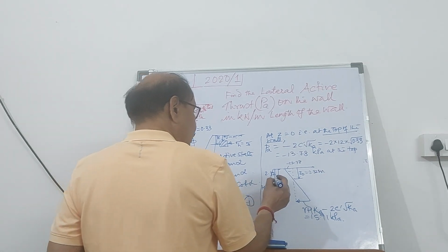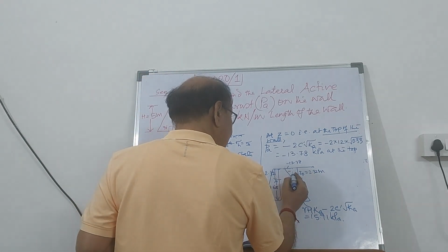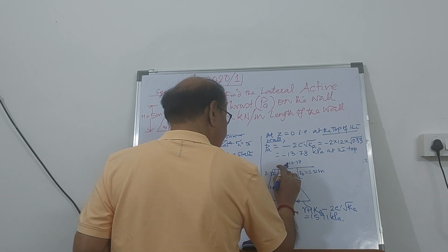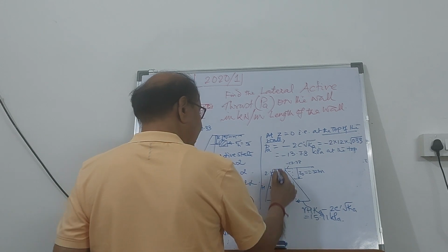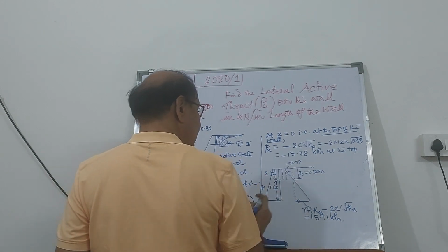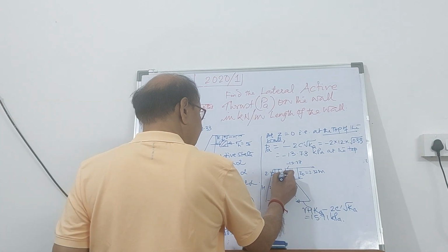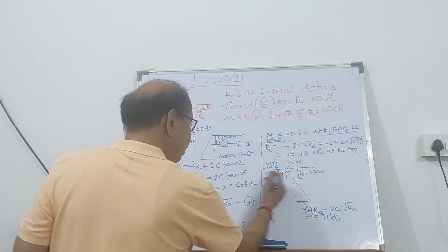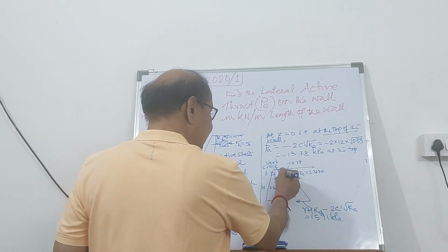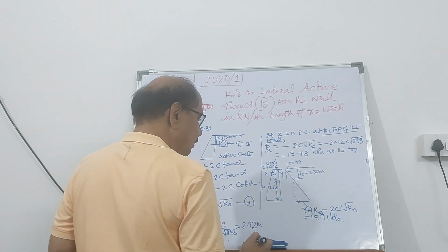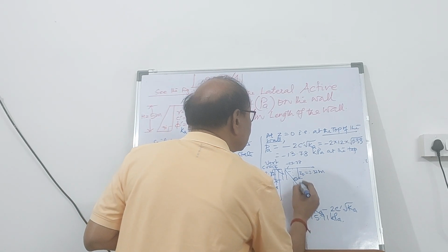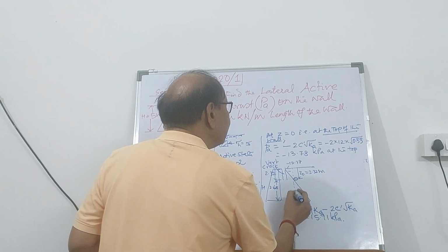So now, because of the negative pressure, you will find there will be a vertical crack like this. In a C-phi soil, you will find there is the vertical crack. So no pressure on the wall because there is a detachment in the backfill. So here it is 0, here it is 15.91.